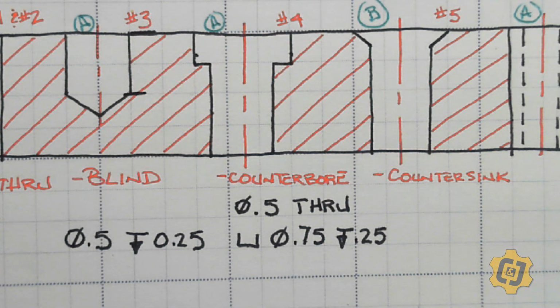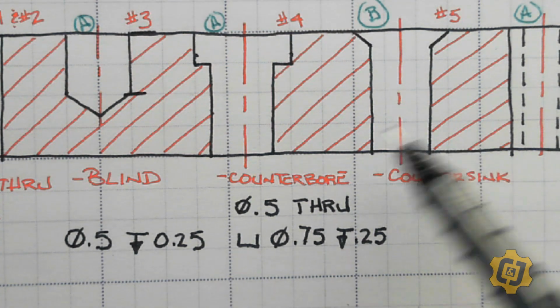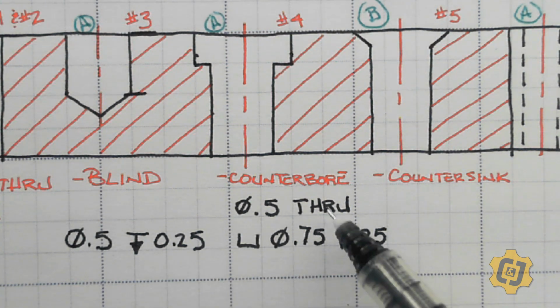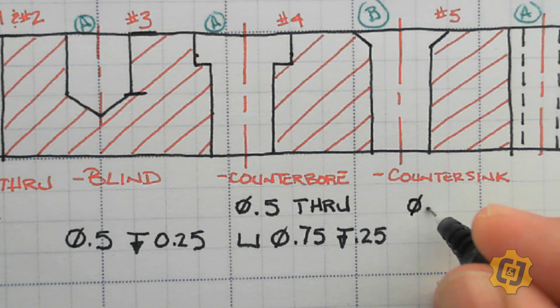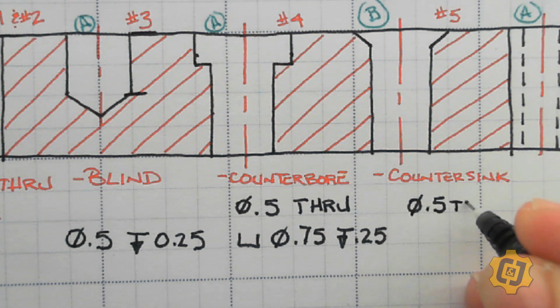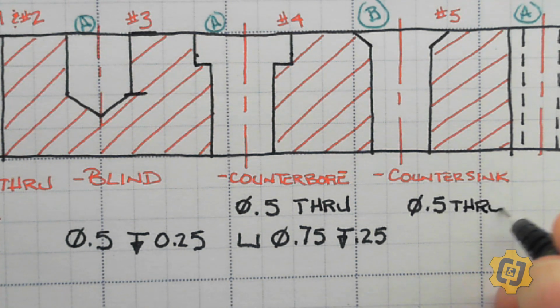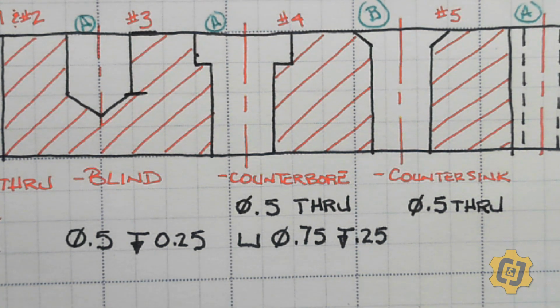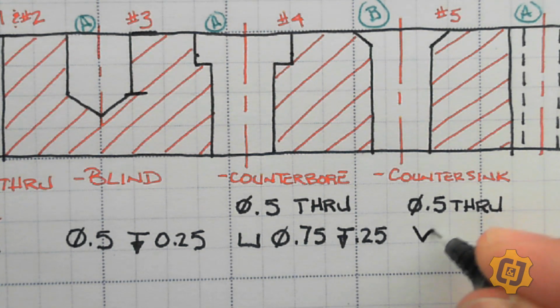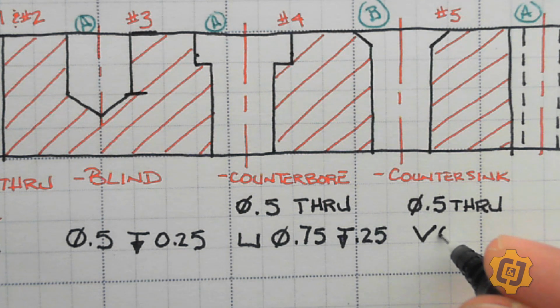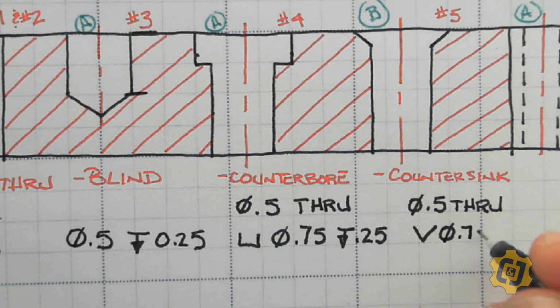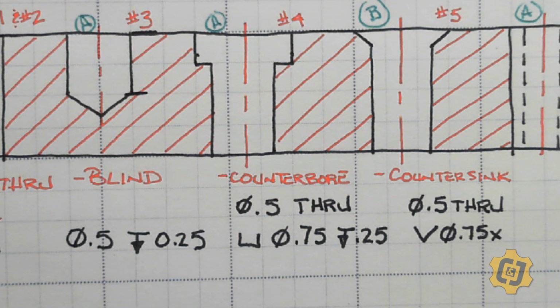Same thing, we started off with the actual hole itself. So however big the main hole is, and whether it's blind or whether it's through, that gets identified. So I'll go ahead and put on my diameter. And then I need to identify what style of hole it is. It has a top that gets that little symbol. That is the symbol for a countersink. I'll then put on its diameter. An X that stands for by in this situation, and then the angle that those two create.